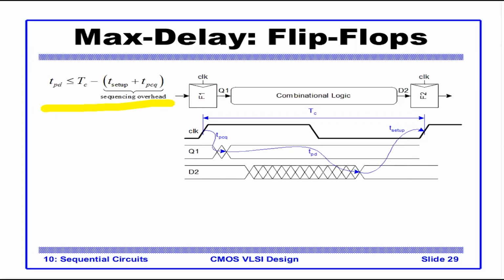So what it says here is that the addition of the propagation delay of the clock plus the combination logic plus the setup time is kind of a delay in this case. This cannot be greater than the period or the frequency of the clock. What it means is that, let's say you have a big combination logic and plus you have some delay of the clock.